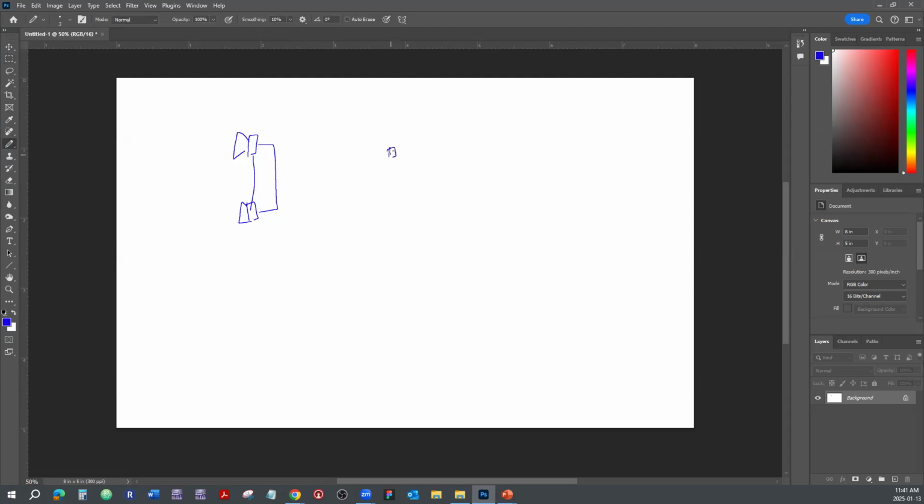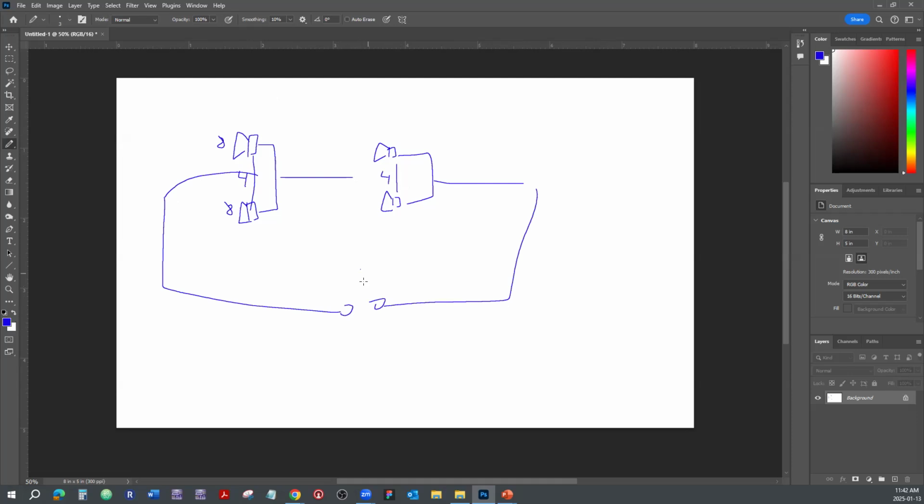Connect these two. Some of you already know what I'm getting at here. These two already also are going to be connected in parallel. So 8 ohms connected in parallel is going to give us 4. Same thing, we get 4. Then we connect these two in series. We're going to add 4 and 4. We're going to end up with 8 ohms, which is what the amplifier wants to see. So that's called series parallel combination. You can do that. Okay, here's 4 speakers.